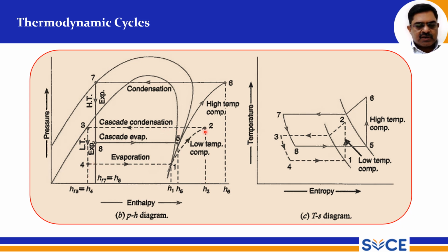The dotted line is LT and the solid line is HT. These are the two offset cycles you have to show here. Similarly here this is LT and this is HT. So this is the distance between these two, and that offset has very high significance, and you have to draw the two cycles with equal offset distance. So this is the thermodynamic cycle for two-stage compression.